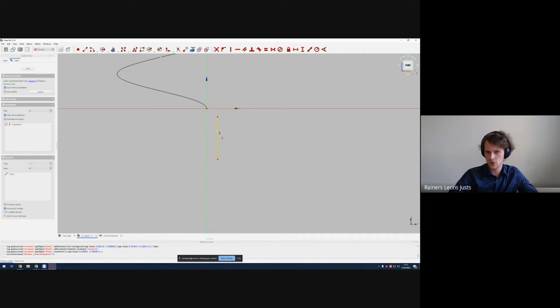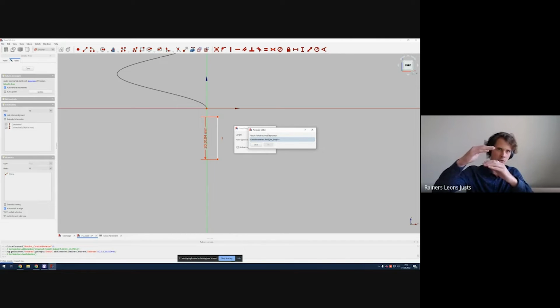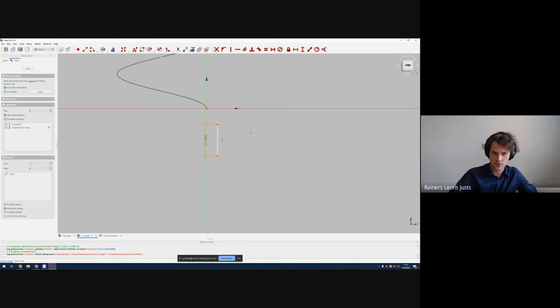So I'm going to be using this feed line also as the inner conductor of the coax. So let's define the length for it. I'll call the formula editor and call the parameters that we need. So first off, we need the feed line length. And then we also need to add the amount of the wire that's going to be inside the coax. So let's call CENOS parameters and add ground thickness. And this will make sense in a moment once you actually start defining the ground plane.